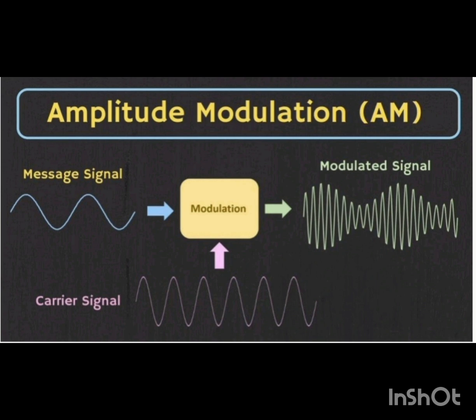It is possible to write an equation for the amplitude of the amplitude modulated voltage. We have capital A equals Vc plus Vm, which is Vc plus Vm sin omega mt, equals Vc plus m Vc sin omega mt, equals Vc (1 plus m sin omega mt).